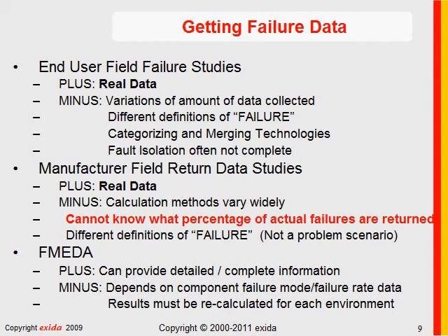So the two metrics are important for each product: the random failure rate as a function of failure mode, and for safety, it's primarily the dangerous failure rate. And then, of course, the useful life period after which a product should be replaced.